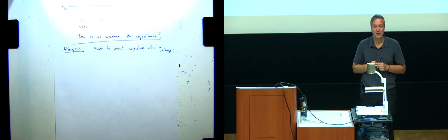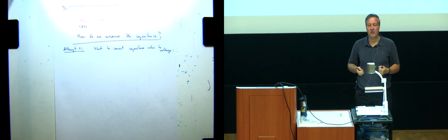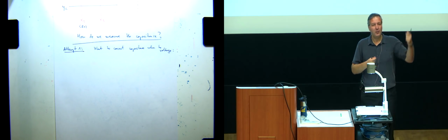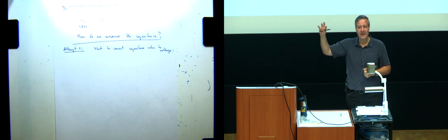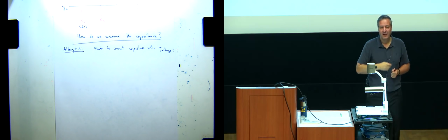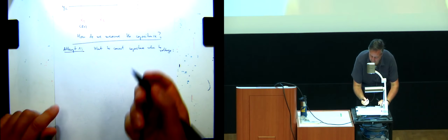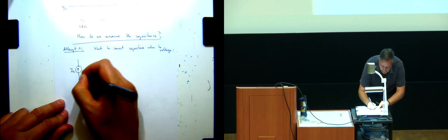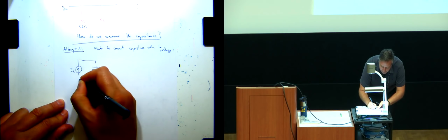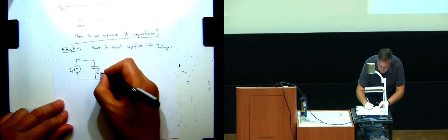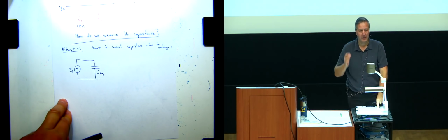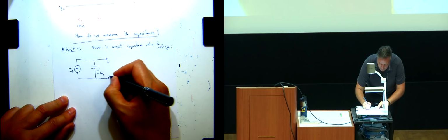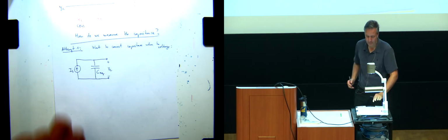When we added a voltage source, a voltage source applies a fixed voltage across a capacitor. It doesn't really give me a new value. I want to apply something so that the voltage contains the capacitance information. Which one? Current source, yes. Okay, so let's do that. Let's say I apply the current, and then there's a capacitor here. This capacitor is this pixel capacitor, so I'm just going to call it C equivalent. And I want to measure a voltage between these two electrodes.